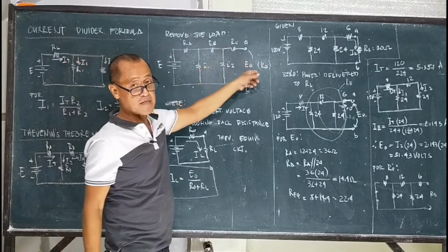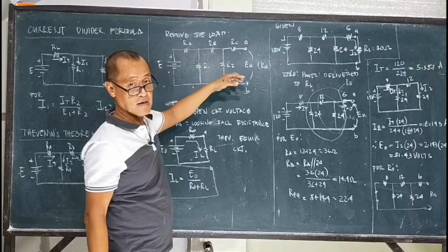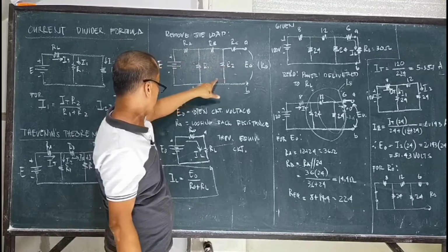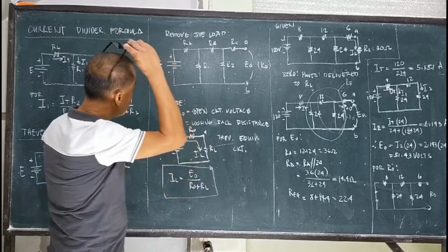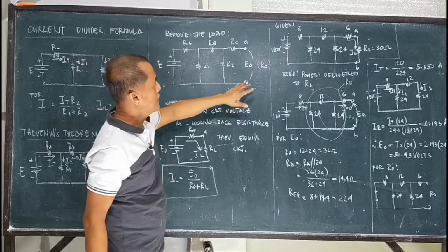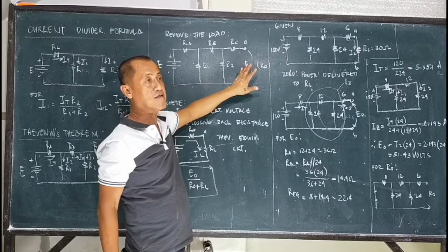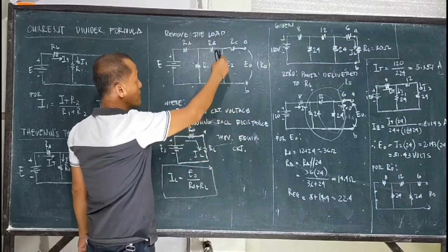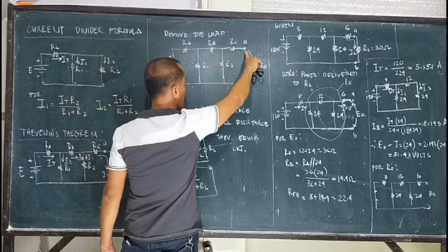Measuring, it means we can also obtain it by solving the currents. In an actual circuit, we open it and just measure the voltage. But with a schematic diagram like this, we have to solve for the open circuit voltage using other theorems. Then, for R sub O, the looking back resistance, this is the same as the equivalent resistance, R equivalent. However, R sub O is measured at the receiving end here.